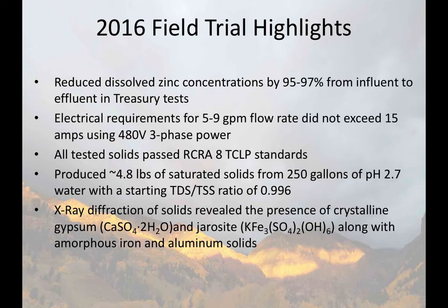Dissolved solids is kind of a weird concept, honestly, once you start really digging into it. We have made this line in the sand that 0.45 microns constitutes dissolved. It's not necessarily a real thing. There are suspended solids that are smaller than 0.45 microns.